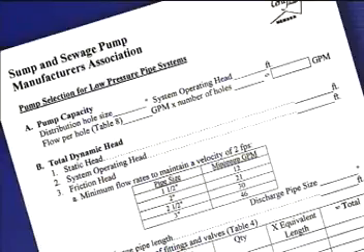Using worksheet number 2 and the tables included in your work materials, let's work through an example. In this system, we have 25 3/16 holes, an operating head of 3 feet, and laterals all at the same grade.